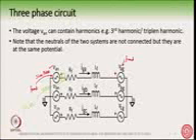Now one of the characteristics of this voltage source, I will call VH, the harmonic voltage source. This is a common mode voltage. It is very important to understand that this is a common mode voltage, which means the same harmonics we are adding to all the three phases at the same time. So these green colored voltages are the common mode.